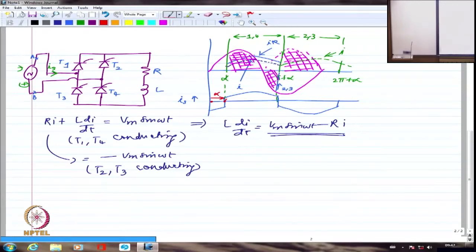We are not starting with transient. I told you that if we start from transient, it will start from zero. Inductance will slowly accumulate energy. We are talking about the waveforms in steady state, and if I am considering continuous conduction. If it is discontinuous conduction, it will start from zero, what we discussed yesterday. I don't know whether you were there yesterday. Yeah, you asked the question also.